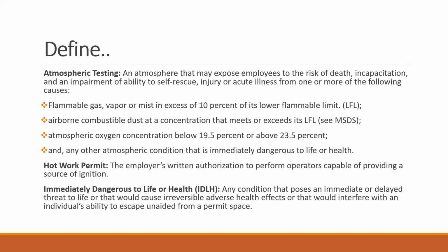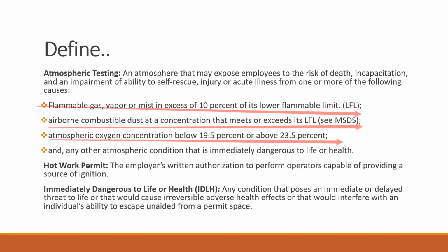Immediately dangerous to life and health is a situation where a person can, for example, get trapped, or he is working at height or in a confined space where there is a certain possibility that he can have an accident and die. So we also call it IDLH: any condition that poses an immediate or delayed threat to life, or that could cause irreversible adverse health effects, or that would interfere with an individual's ability to escape unaided, right?